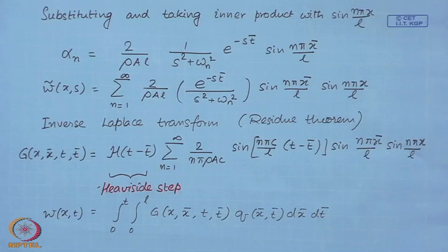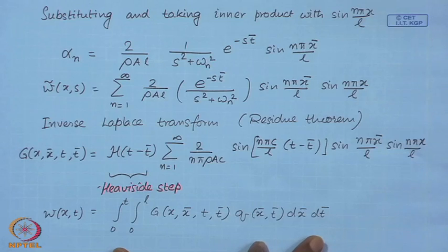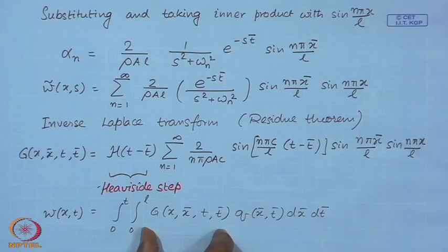So, this is a very powerful method of approaching forced vibration problems with arbitrary forcing. Now, we know how to solve using the Green's function method. Here we have used the modal expansion technique to solve the boundary value problem. In a previous lecture we have seen how the Green's function was solved in a different method.